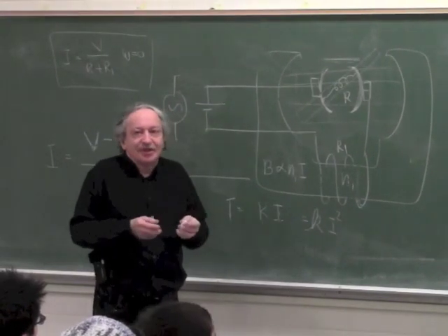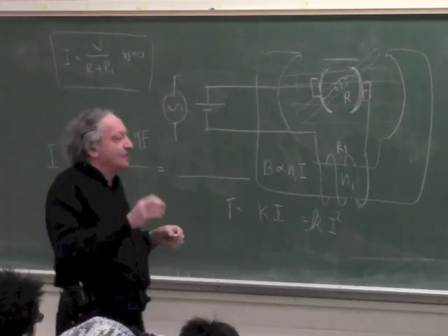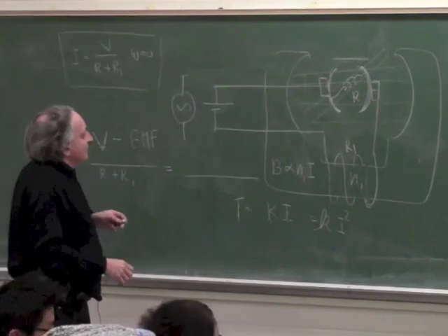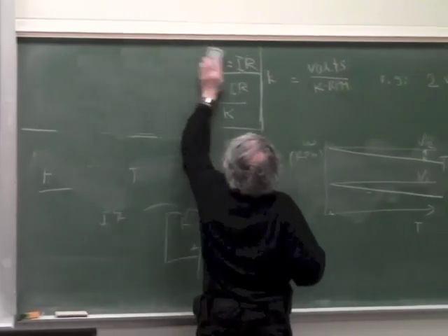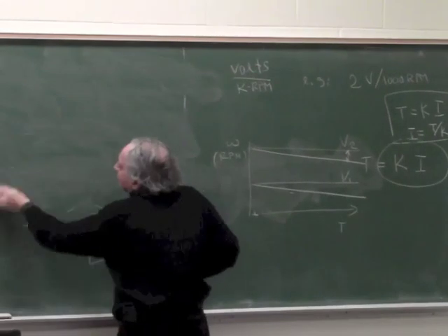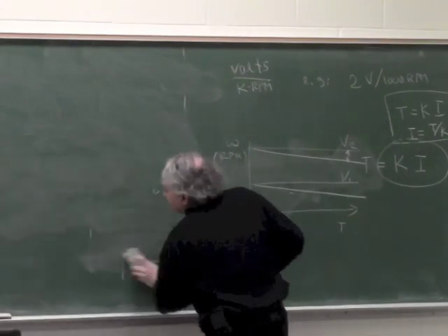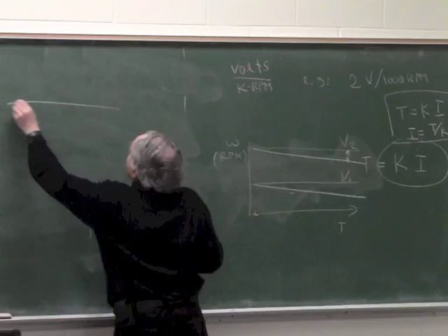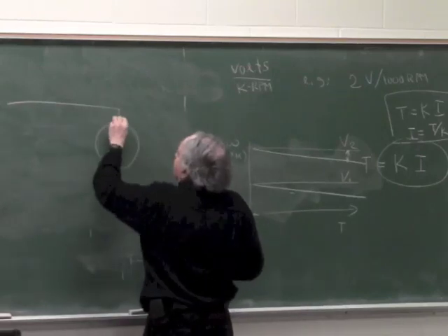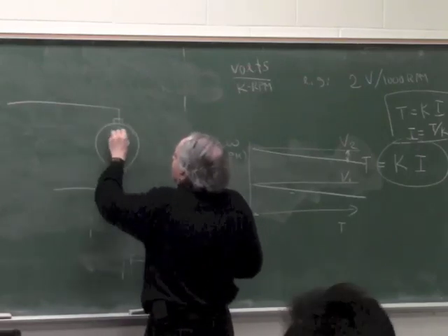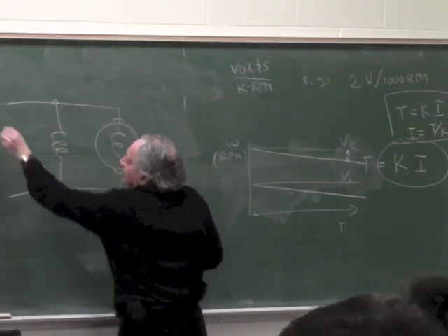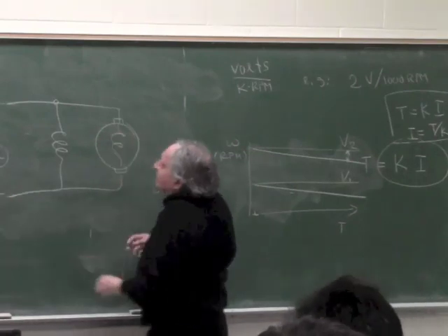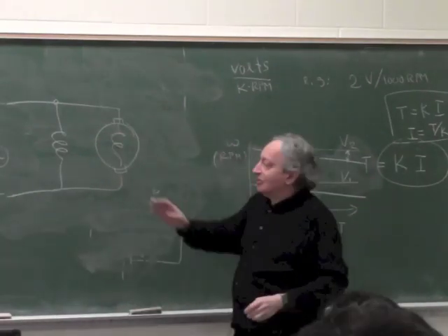Okay? Now a very subtle question. So the series wound motor can be run on AC, and I already mentioned last week that the parallel motor, if we take a PMDC motor but instead of a permanent magnet, we use a shunt wound motor, we said it can also run on AC, because of the same argument.